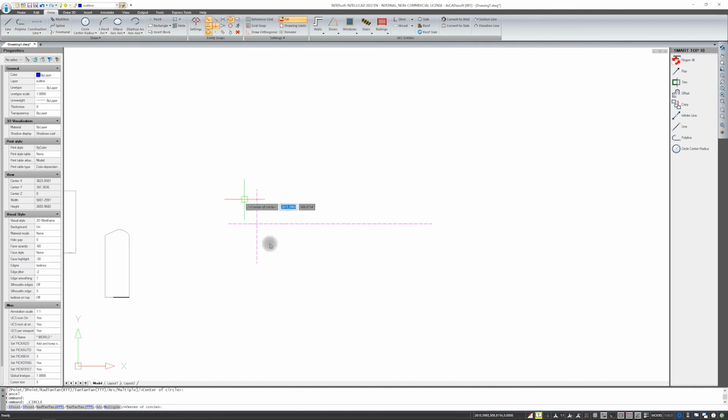Now I would like to discuss some more basic elements for precise drawing. It could be the grid that I turned on here. It could be ortho drawing, because drawing ortho is very useful. But to find the intersection point where I want to start drawing, I need to have the snap point turned on. The snap points independently select the characteristic places on the elements, whether it will be the end of the line, center of the line, or the center of the circle, or the center point of the arc. You can turn all these elements on and off so that the program finds them.